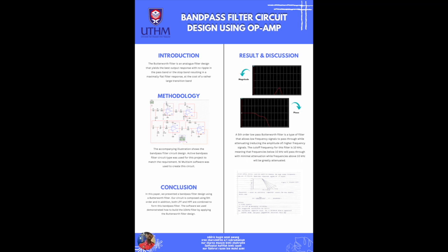The cut-off frequency is set to 9.75 kHz, and the standard capacitor value for audio circuit design is chosen to be 0.01 microfarad.